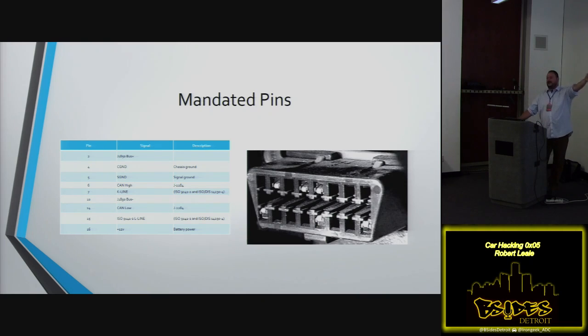The Fiat pin 1 is not single wire CAN because it's a different OEM. So each OEM has sort of a different look for this connector. And their motivation behind it is really quite simple. This is their port. This is their interface for their scan tool to plug into their cars, right? And so all that discretionary pins are going to change because the OEM has a scan tool that is expecting certain information or certain things to be on these particular pins. And so it's for them.